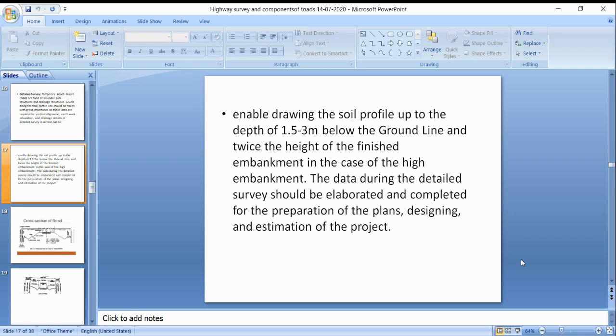Around the width of the road, for 30 meters width, we have to decide for any river crossings the alignment has to follow, because only on the hydrological details does the width of the road depend. We also have to see any quarry sites, and any soil surveys to be carried out.